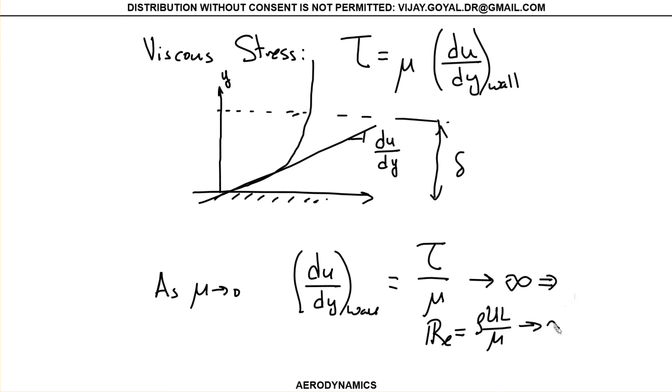It's also going to tend to infinite, if you realize, right? But this is 0, this is also going to go to infinite. So what does that really mean? It means that if this goes to infinite, your boundary layer is actually almost horizontal. This is what's happening to your boundary layer, it's almost horizontal. It's going all the way up. All you're saying, basically, is that all your flow is turbulent. Okay, you have an infinite Reynolds number.